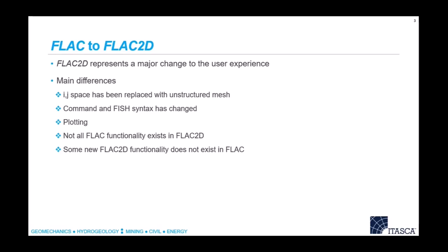What we now have is officially a finite volume program, which means that we can have these unstructured meshes, and you've been seeing that all week. And this just makes life easier in so many ways, because you just say mesh and you get a mesh, and you don't have to try and fit it to this perfect grid. We have been doing some examples where you try to make these structured meshes, right, by creating four-sided shapes and filling them up, and you get nicer meshes, but you don't have to, which is nice.